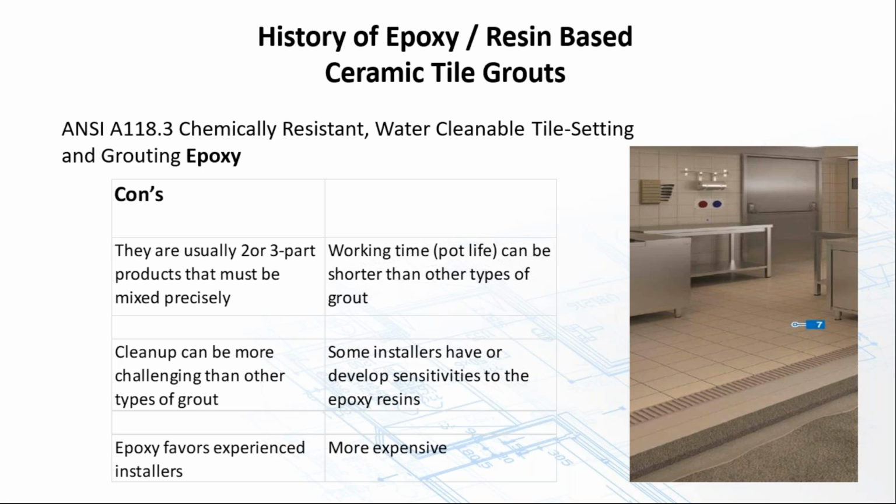There's a shorter working time. Of course, pot life, because as I mentioned earlier, it's a thermal set. If you don't get the grout out of the bucket, it can start setting off and giving you less working time with it.